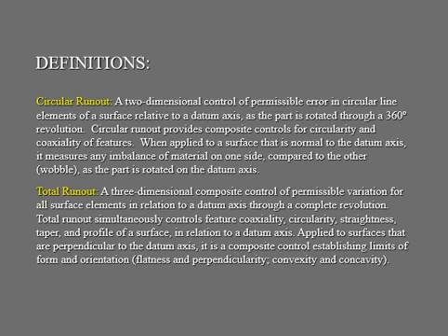First, we will get into the circular runout, and the other one is total runout. They're just two-dimensional controls. We call it control because they control the features on the part in many different ways. Then we break it down into profile, circularity, perpendicularity, parallelism, and so on. So now we come into runout, another two-dimensional control to make sure that we're manufacturing the same thing as we draw and design.